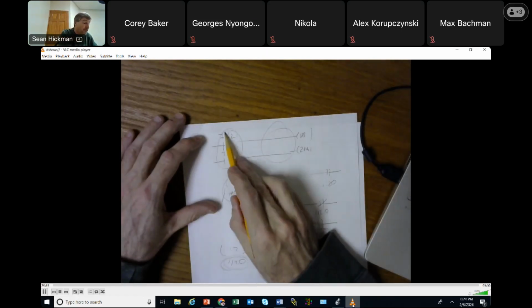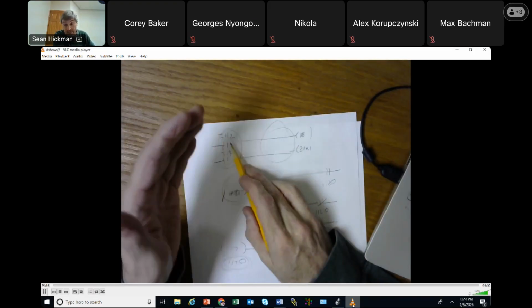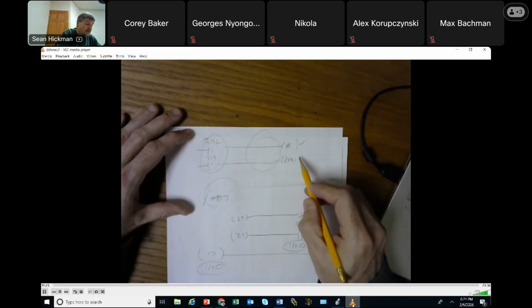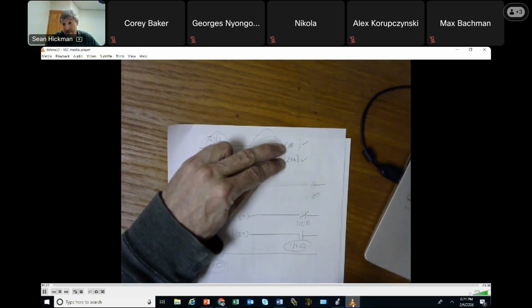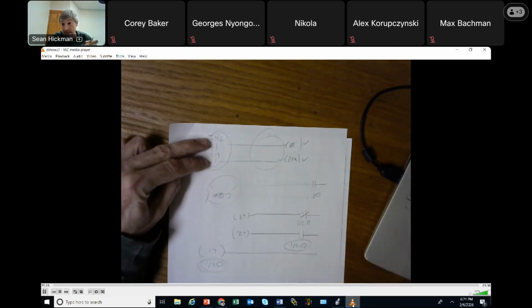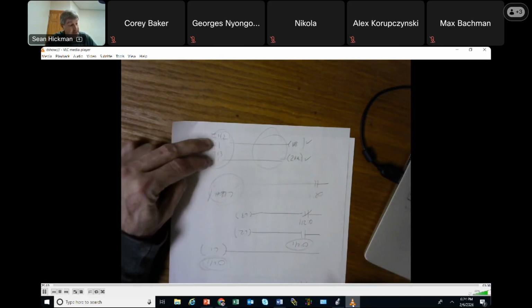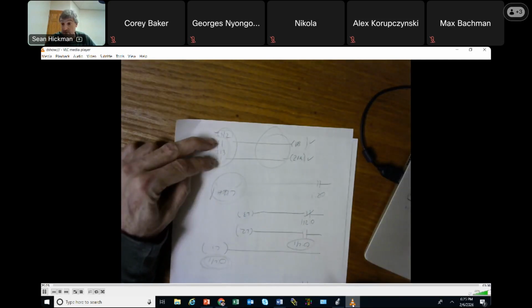But as soon as I take this right here, that is its own scan and is getting updated, it means that these bits right here, because these are no longer, these are just tags, they're just bits. These get created immediately during the input scan, and so now all these exist fictionally as soon as the input scan is complete.